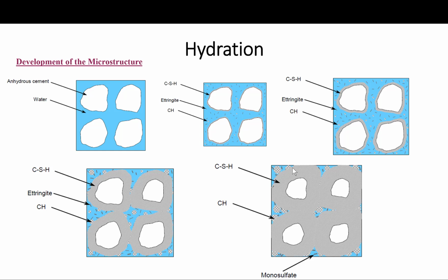A schematic is shown here. This is an idealized and simplified approach, a proposed model of what goes on when the cement is mixed with water. When the Portland cement is dispersed in water, the calcium sulfate and the high temperature compounds of calcium begin to go into solution, and the liquid phase gets rapidly saturated with various ionic species as a result of the interaction between the calcium sulfate, the aluminate, and the hydroxyl ions.